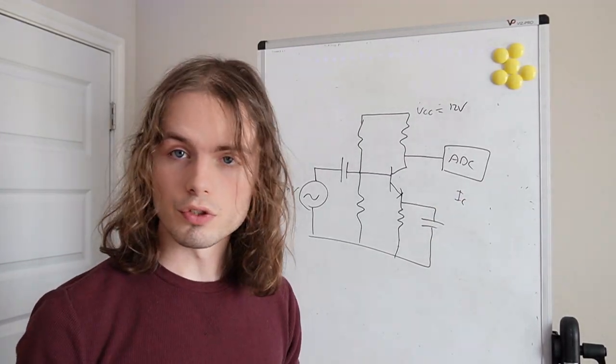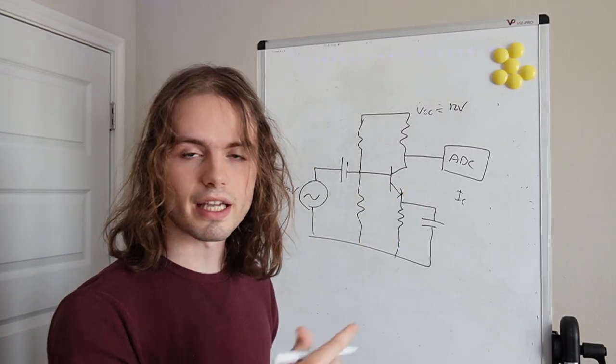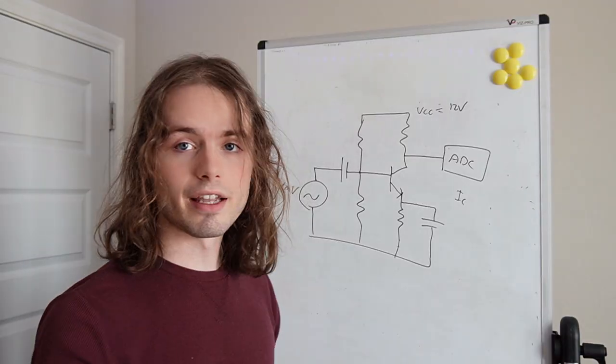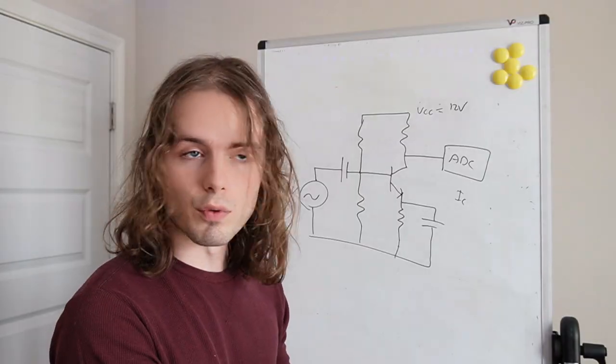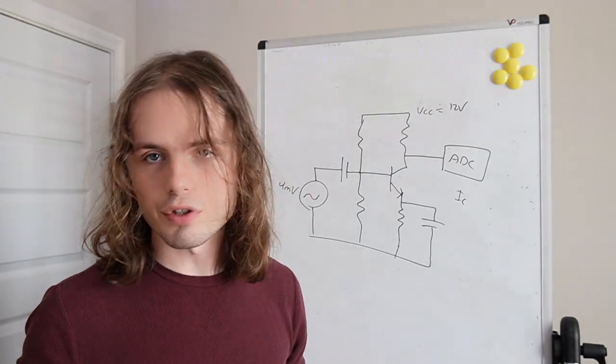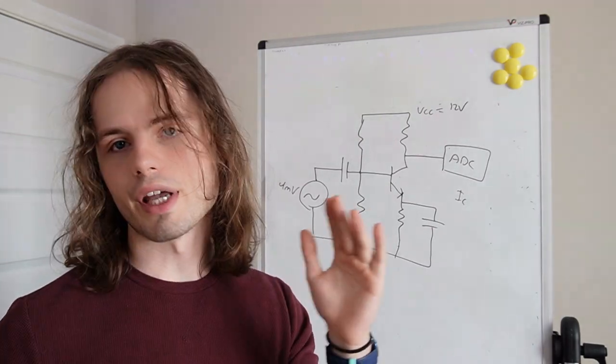The one thing that we could make a choice on is that transistors typically have different gains for different collector currents. So they vary between 40 to maybe 500 or something, and depending on how much collector current it is, you may be somewhere on that curve.